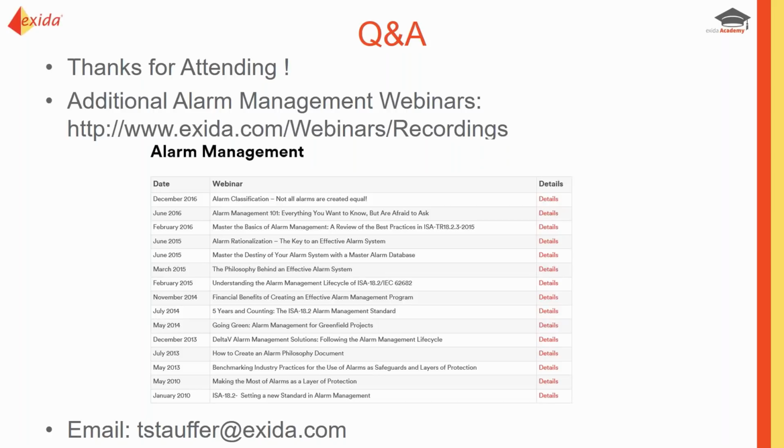Then there's a question: is alarm rationalization, alarm masking, or other activities part of this package? It's a great question. They're not part of the XLReporter tool, but the XLReporter tool is an excellent input to those activities. And those activities would go on separately. They're a different stage of the life cycle. Alarm rationalization can be done with the SIL alarm tool. That can also define some advanced alarming, alarm flood suppression, and state-based suppression requirements as well. And I think that is it for the questions.